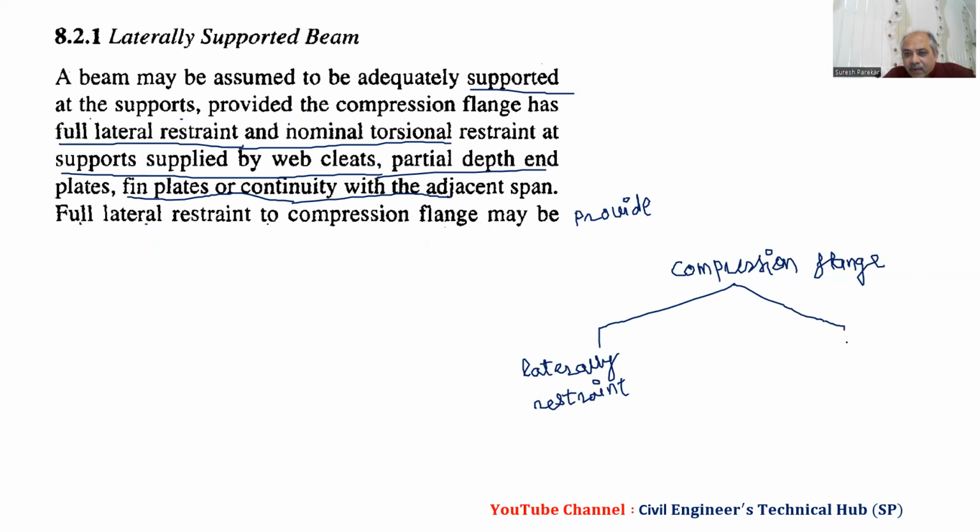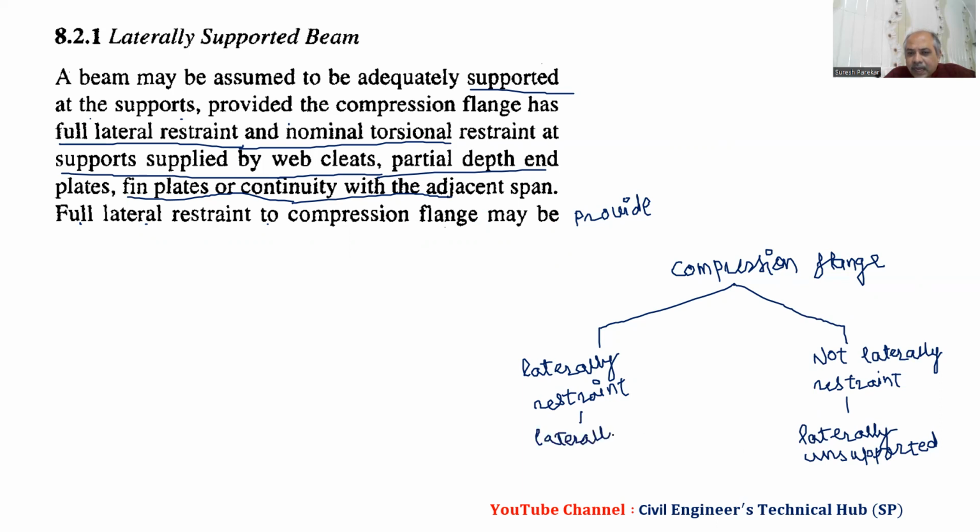If my compression flange is not laterally restrained, then I will say it is a laterally unsupported beam. Unsupported means not supported, and laterally supported or restrained means laterally supported. What does it mean? Laterally supported means lateral deformation is prevented.